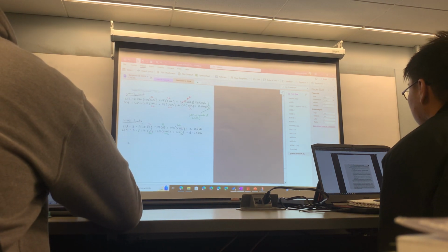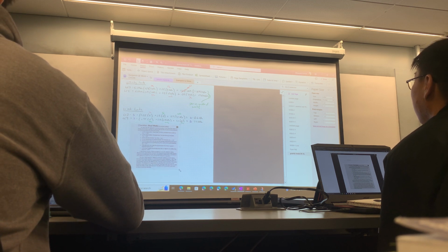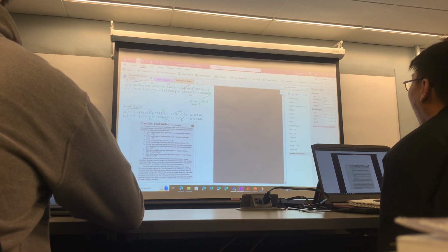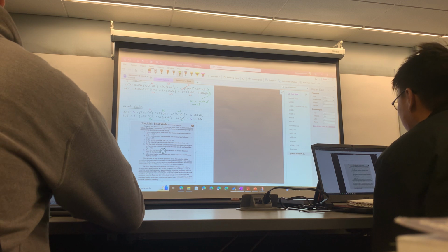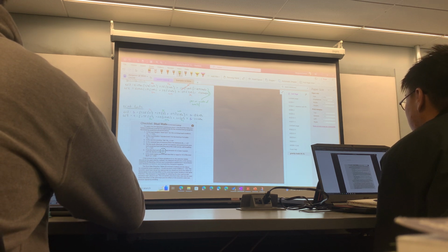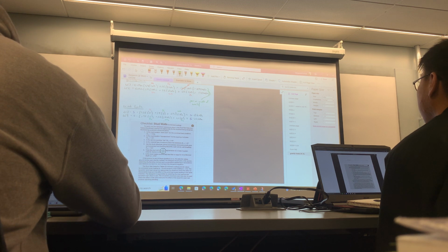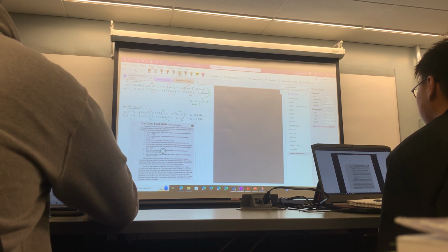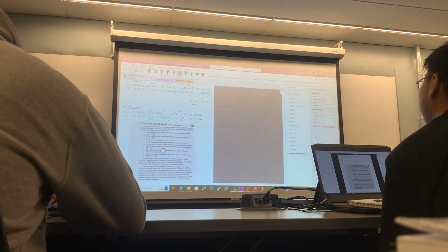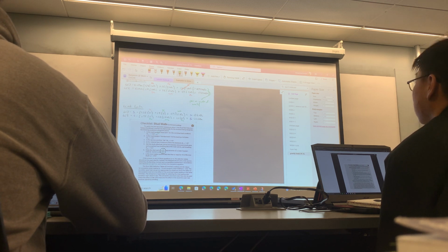So now we're going to check our checklist, and you'll see it's a little different than what we're used to. Is the load duration short term for the combined loading condition? The combined loading condition means both loads are acting at the same time. We know gravity loads are not short term. Snow is going to be there for a while, and dead load is definitely going to be there for a while. But the combination of that gravity load with the wind at the same time, is that going to be short? Yeah, it's a very minimal time. So we can say 1.5 is good.